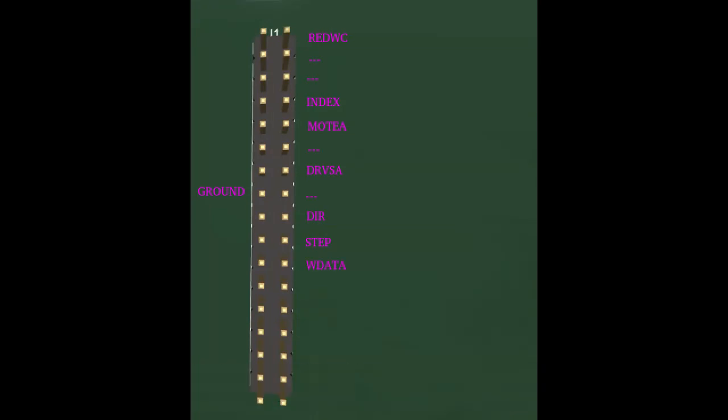Pin 22, write data pulses. Pin 24, write enable. Pin 26, track 0 indicator: 0 volts, the head is above track 0. Pin 28, write protect: 0 volts, disk protected. Pin 30, read data pulses. Pin 32, head/side select. Pin 34, disk change: 0 volts indicates ready to work; 5 volts, disk change.